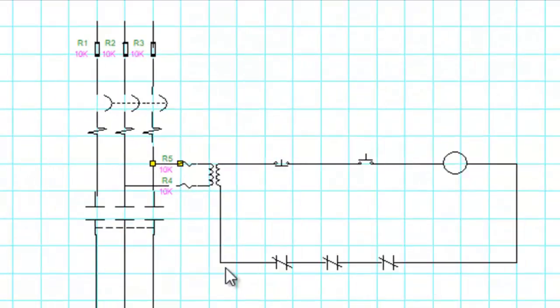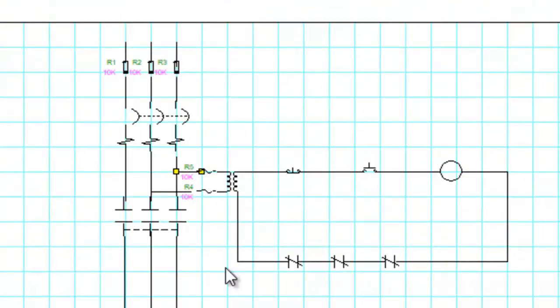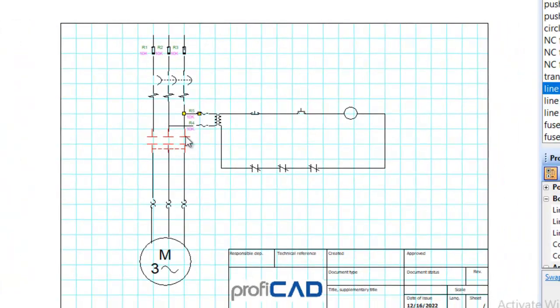So now, if we want to start our motor, we will put on the circuit breaker first. That means that we now have power to our control unit. Okay. Then this start button, once you press on the start button, that will close the control power to the contactor coil. This contactor coil, the circuit to it will now be complete and it will be energized. Once it's energized, the contactor contact will do what? Will close. And as it closes, power will now flow to your electric motor and your electric motor will start.